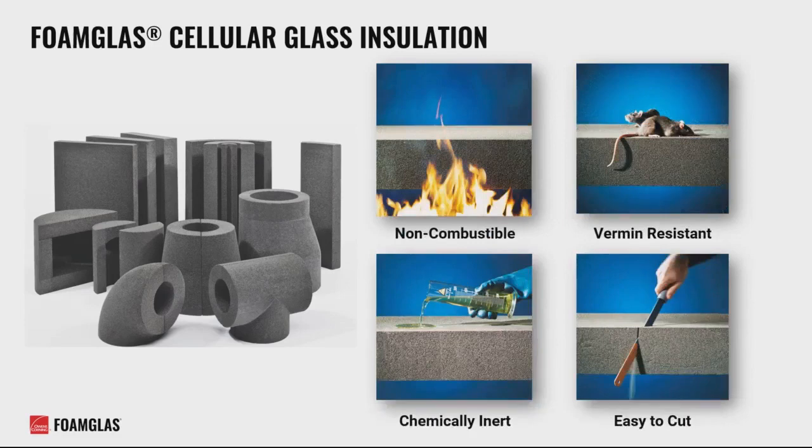Being 100% inorganic and made of glass, foam glass is non-combustible and does not give off dangerous gases in the event of a fire, making it suitable for fire protection and fire stop applications. It's also resistant to the nesting activities of common vermin that may be found in an area, and is chemically resistant in a similar fashion to many typical glass beakers you might see in a laboratory. Finally, it's easy to cut and can be prefabricated to many different shapes and configurations prior to arriving on a job site.